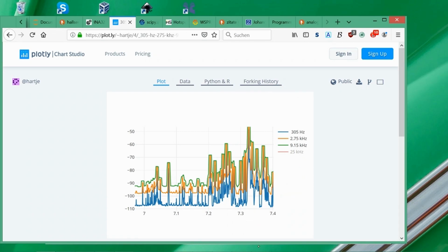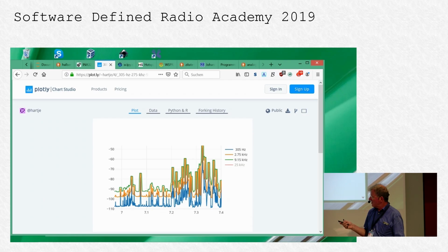The next step is to find out how we can estimate the noise level. The noise level can be thrown out optically, it is very clear. But in the WSPR decoder, I know the one of Steve Franke, he has an idea to just calculate the statistics of the signals we measure. He sorted it and then decided we take a level of a few percent, and everything below is noise level, everything above is signals. And so it calculates the signal-to-noise ratio. But here we want to make a similar adaptation of this to find out the noise level. This is our optical view, minus 108 decibel.